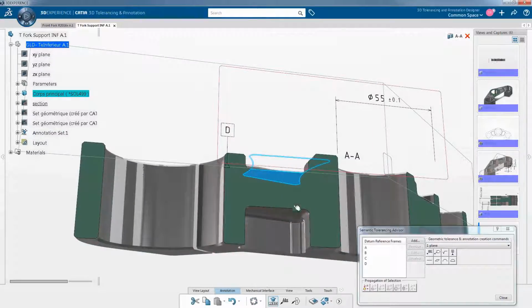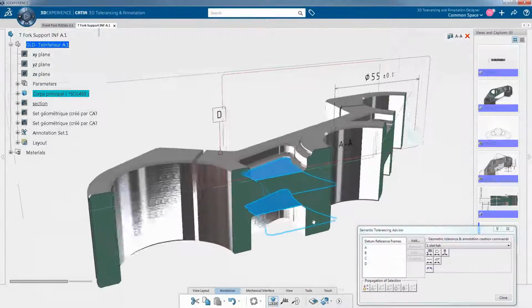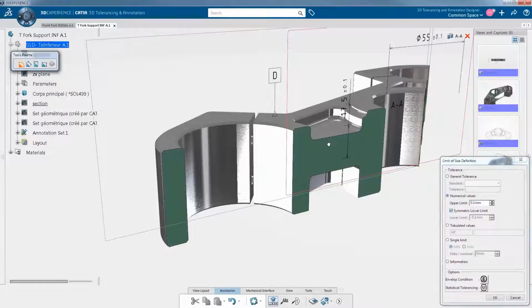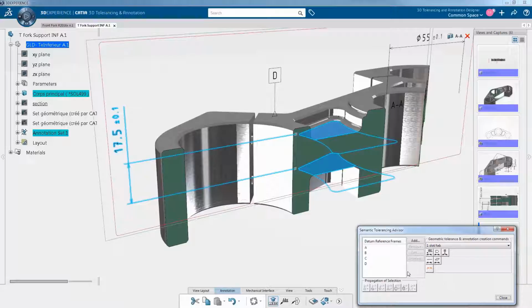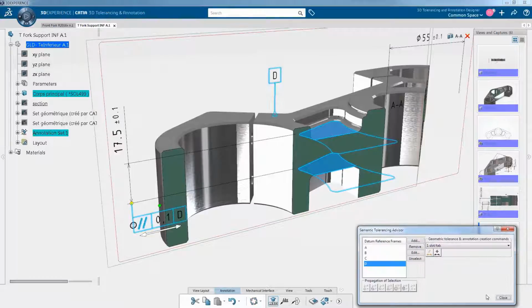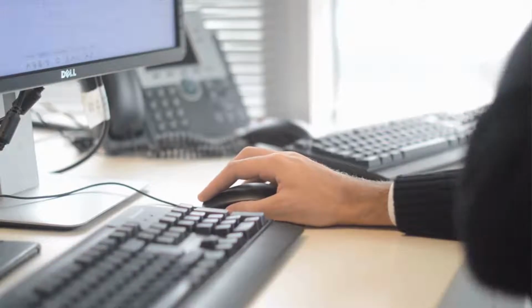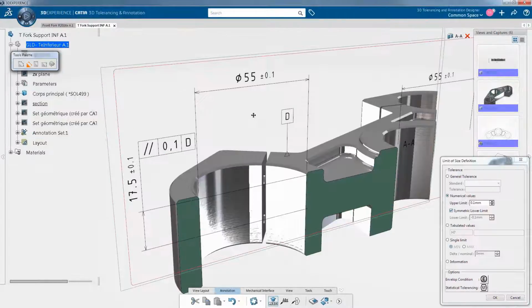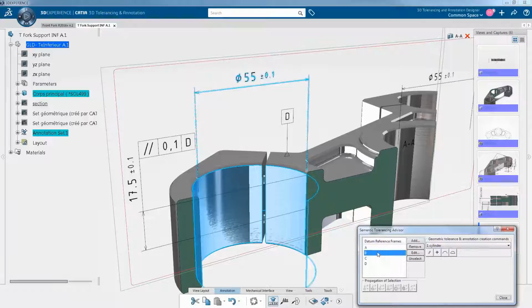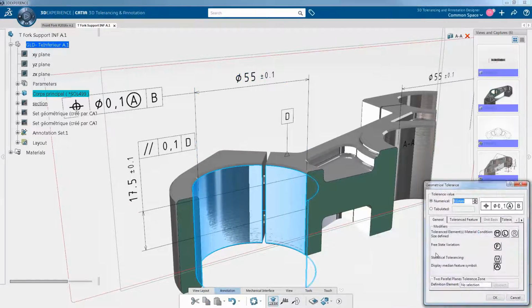Between those two selected planar surfaces, the advisor recognizes that they are parallels and proposes a distance dimension so you can specify tolerances. Now you would want to select the parallelism specification as datum D. You select the parallelism and specify the tolerance to complete. Now you can continue in this manner, helped by the advisor, to create the rest of the dimensional definitions. Now you can continue to complete the definition tasks. Specifically, select the capture to be completed, activate it, and continue defining tolerances.